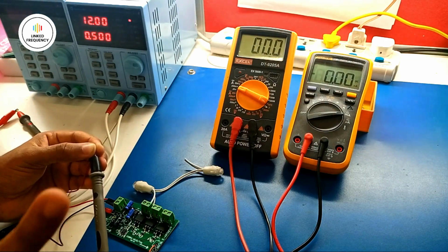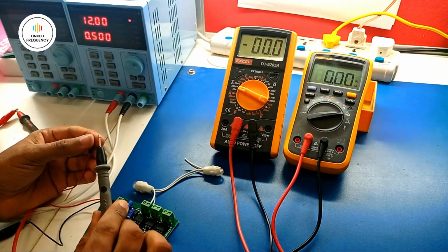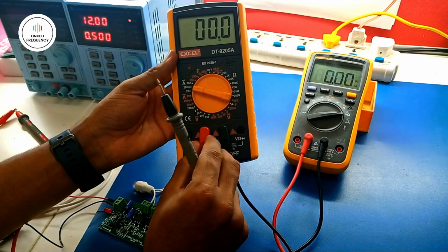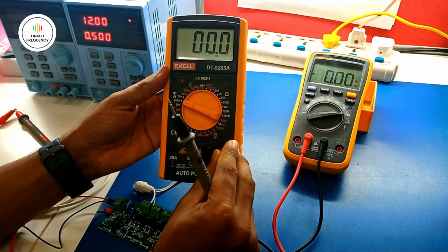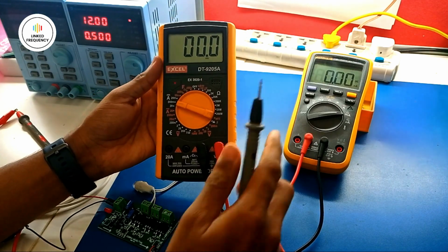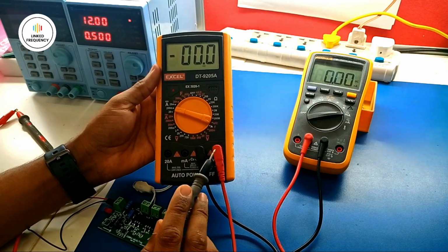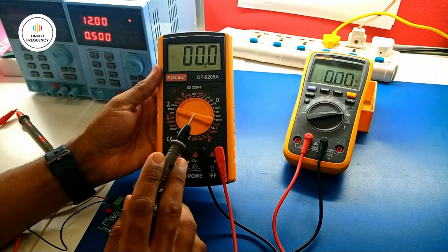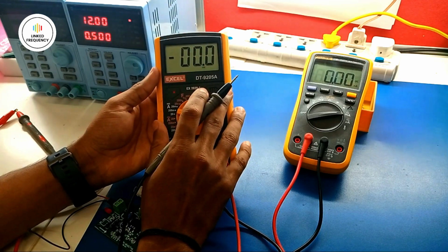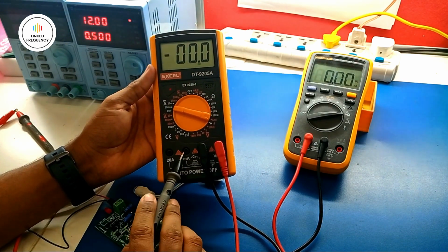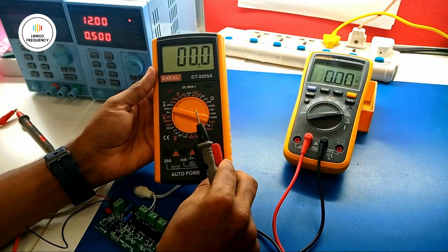Alright, now once you are done with measuring current or voltage, whatever it is, make sure that you unplug and plug the positive probe of the multimeter back to the voltage point by default, because whenever the next person is using this digital multimeter, if he or she does not see this positive probe and connects it to a voltage measurement, then it will damage the entire multimeter. Best practice is to always keep the positive probe at the voltage point of the digital multimeter.